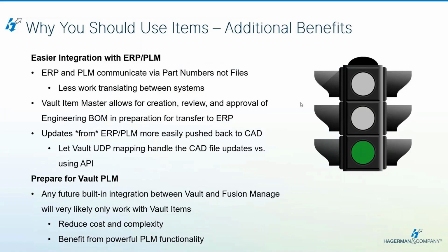You can also get your BOM sorted. If the goal is to send our BOM to some other business system, you can get the BOM sorted outside of CAD. You can do all of that in the Vault interface without having to crack open Inventor and open a 1,000-part assembly. It's just right there inside your Vault, right?